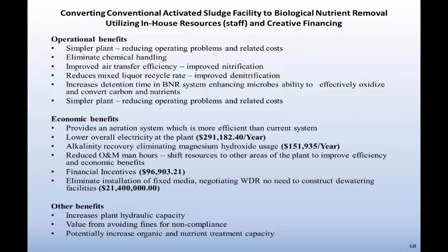In addition to that, it also helped us to reduce our return activated sludge rate from approximately 80% to approximately 30%. By doing so, we were able to secure 5 return pumps and not only operate with 1 pump. So that's huge energy savings there. And also it increases the life of your equipment.